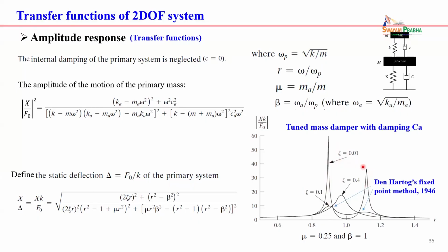can we have the opposite effect? Small mass keeping, vibration increasing. You mean the opposite direction? Yes. Putting another mass, we are damping. Is the reverse possible? We can increase. A small mass can increase the vibration too. Or you can say it that way, right? Like when damping is small, at this frequency it will increase the vibration. Right? Here in the middle part, you reduce that. Okay. So it depends on the excitation frequency, right?